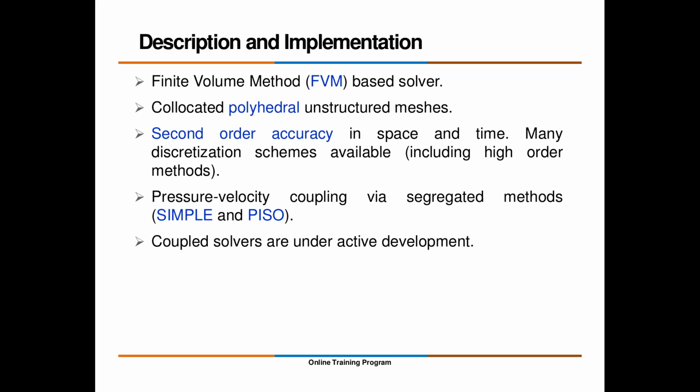It is second order accurate in space and time. This type of discretization is available, and some classes of higher order discretization methods are available. Pressure-velocity coupling algorithms like PISO and SIMPLE are available, and if you blend both of them, it's called PIMPLE in the terminology of OpenFOAM. Coupled solvers are under active development. People are developing coupled solvers.